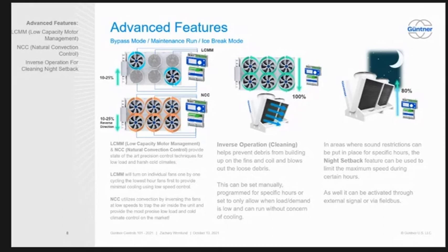Go ahead, Kevin. So how does it know that it's losing that natural convection? Because we can tell that the fans are spinning in the direction they're not supposed to, and we can sense that. So we're going to tell the fans, listen, you're spinning in the wrong way. You're not supposed to be. Spin backwards to lock it in.